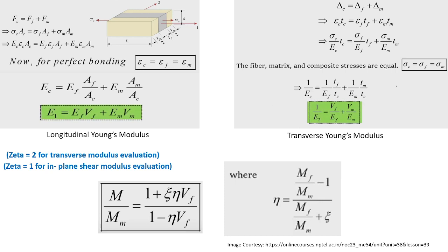It has certain characteristics: if the fraction of fiber is less, then it will fail first, because matrix doesn't have much strength compared to fiber, but excessive fiber is also not good. Even though increasing the volume fraction of the fiber is beneficial for the composite, too much fiber is not good, as there will be less bonding between them, since the volume fraction of matrix is less.